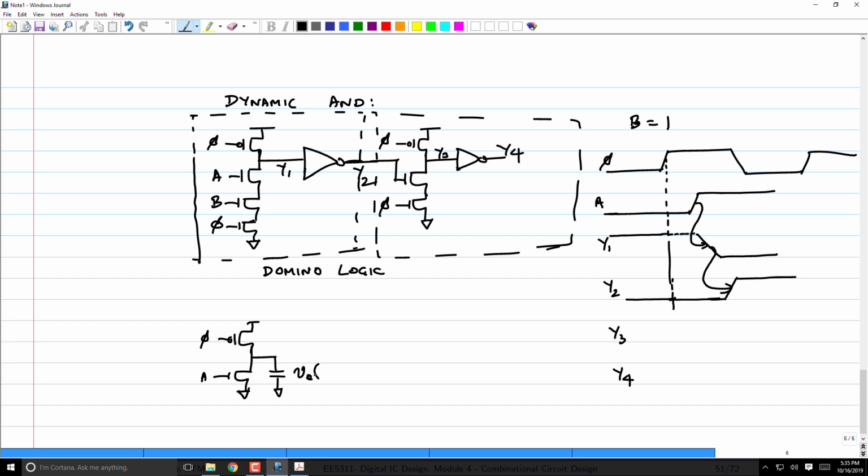VC of 0 minus. Now there is a pull-up path to VDD through leakage of PMOS. Then there is a leakage through NMOS. These two are going to fight and the eventual value will actually not come down all the way to 0. It will come to some intermediate value between 0 and VDD depending on these two leakage currents fighting.